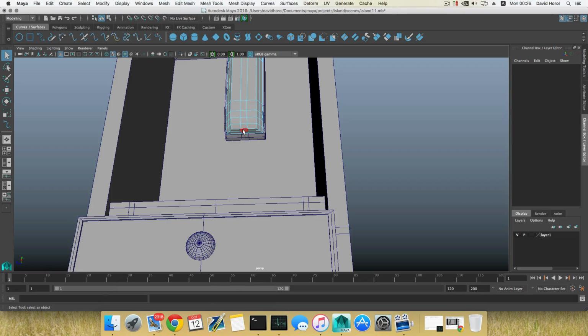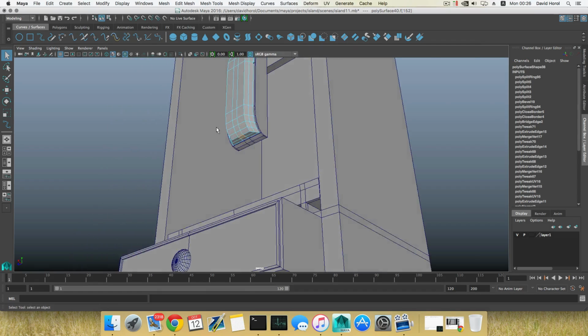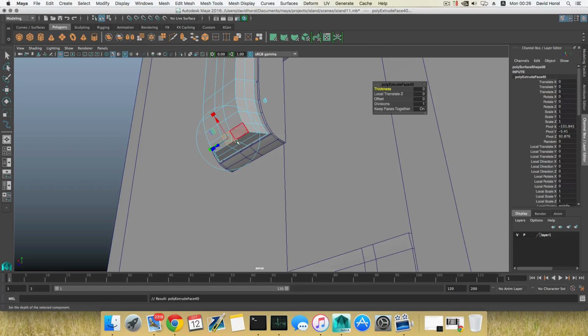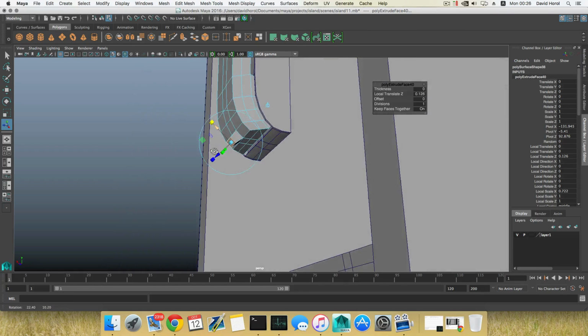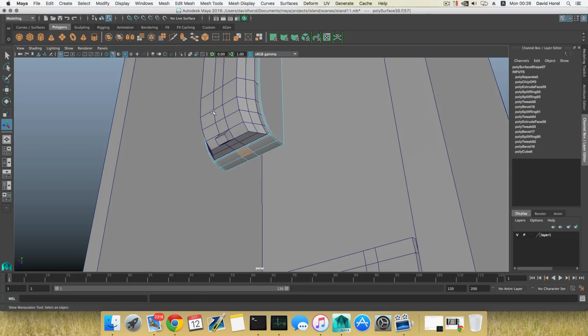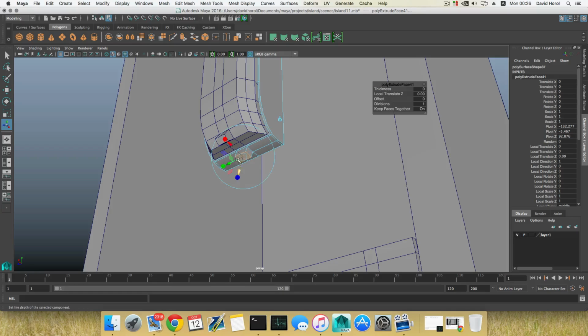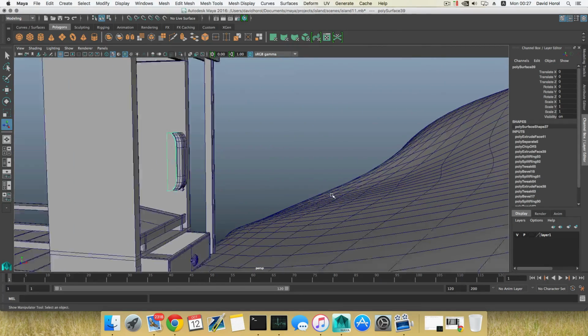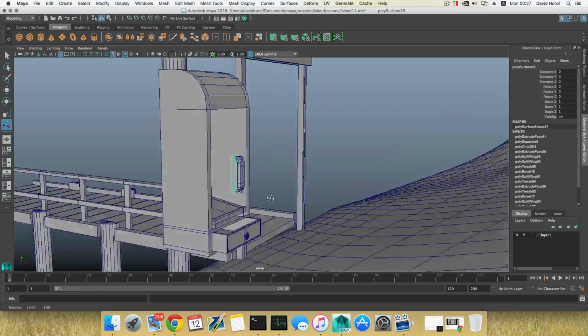So I'm gonna start with taking this face down there, or maybe this one. Switch to polygon shelf and extrude this. I'm gonna extrude it just a little bit and squeeze it maybe a little bit that way. Nothing more than that. We're gonna do the same here to this face. So extrude this. Bring it like so, like that, and this can always be tweaked later on, whenever we will need this to be tweaked that way.